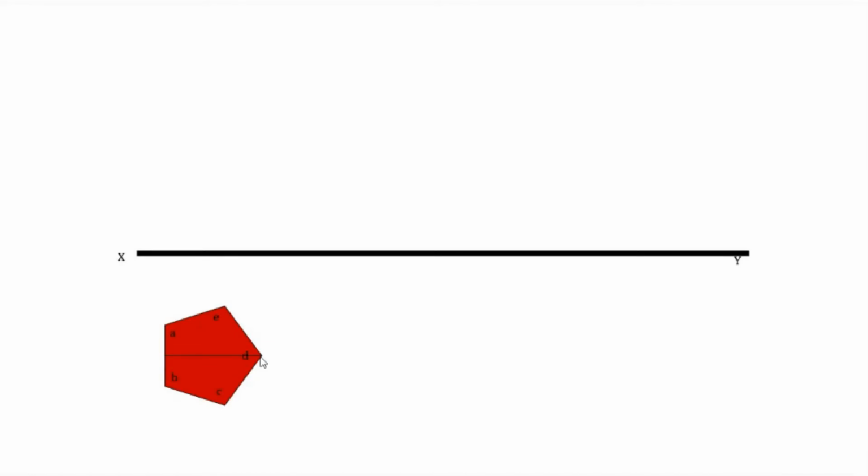So then the naming is done, A, B, C, D, E, and 1, 2, 3, 4, 5. A, B, C, D, E is the bottom points, and 1, 2, 3, 4, 5 is the top points. So then A dash, B dash, C dash, D dash, E dash in the front view. To get the front view, from all the corners we draw the projectors.